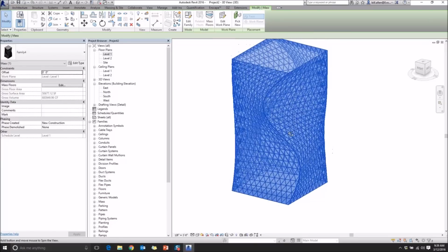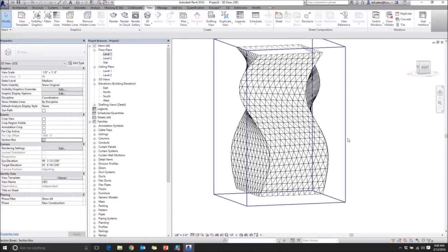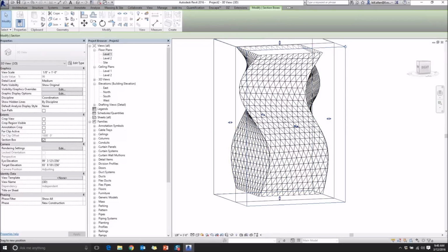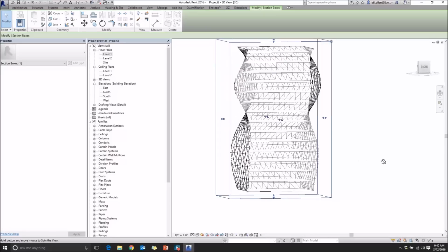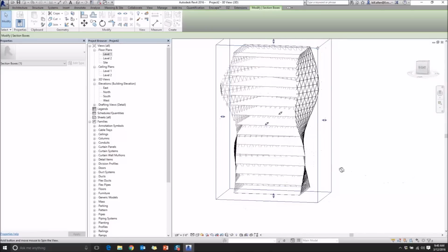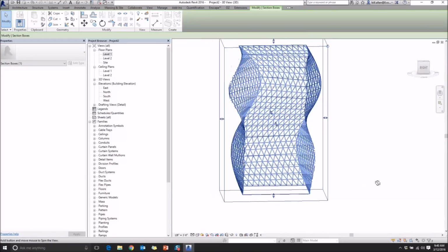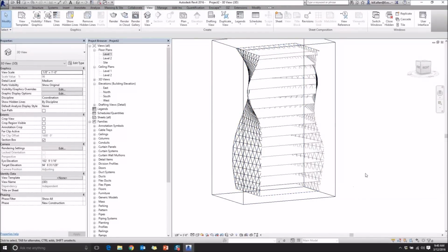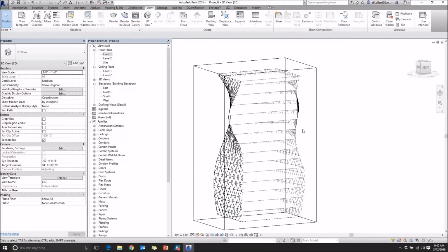You see that? Now let's create a section box, and I pull this in a bit. You can see I have my floors and they're going right to the edge. It's a really nice way to create your floors without having to click every single one of them and go to the face. So this gives me the geometry, but we're actually already starting to create data from this.